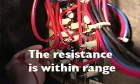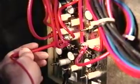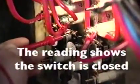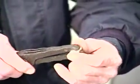The resistance is within range. Since the heating element is not energized, the limit switch should be closed. Check that next. The reading shows that the switch is closed. Now you know for sure the only problem with the strip heater is 2 bad fuses. Before continuing, explain the problem to the customer, estimate the cost of the repair, and get the customer's approval. Then go ahead and replace the 2 blown fuses.